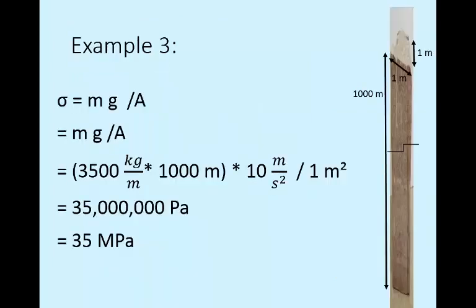The 3,500 kilogram rock had a height of 1 meter. The depths of our mines, or drill holes for oil, are on the order of magnitude of several hundreds of meters to kilometers. So I stretched the photo I took of the 1 meter tall block, and now we can assume it is 1,000 meters tall. The stress under that size rock is 35 MPa.